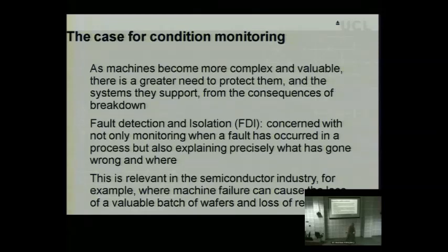Well, this is the problem I said this morning. I haven't said anything about noise here, and clearly there is a problem because one type of thing is an actuator or sensor fault. Another thing is sensor noise. And depending on the characteristics of the sensor noise, your sliding mode observer may try to track them. So noise is a problem for sliding mode observers in this fault detection framework.